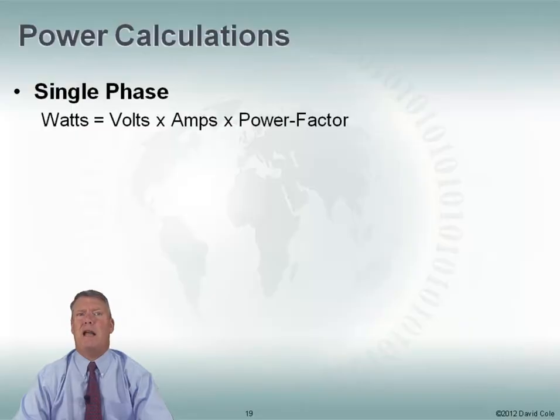Let's look at a couple of power calculations. If I want to calculate watts for single phase, my number of watts is equal to volts times amps times my power factor. Right?